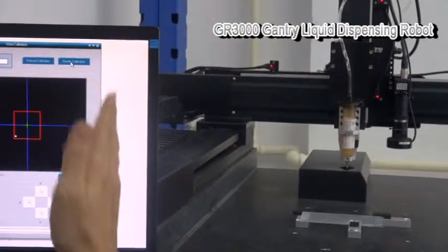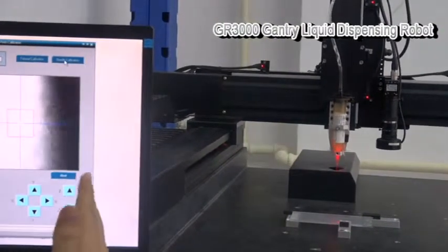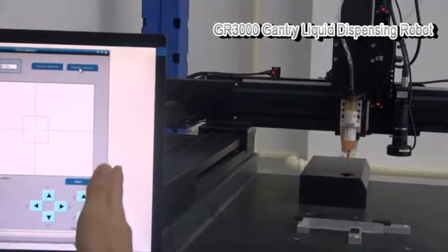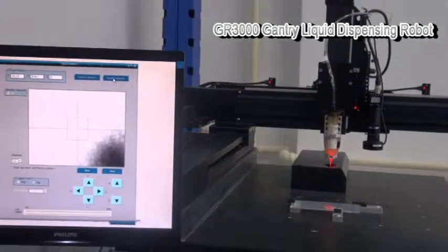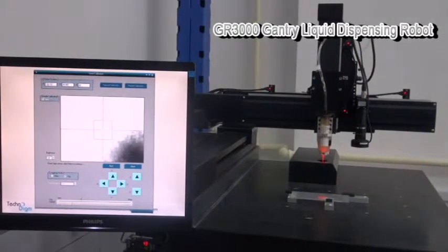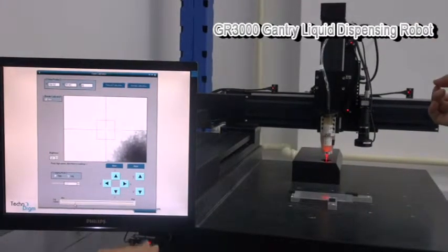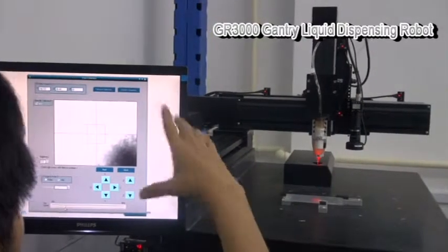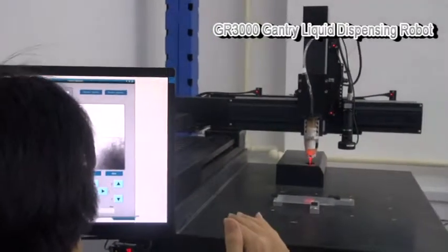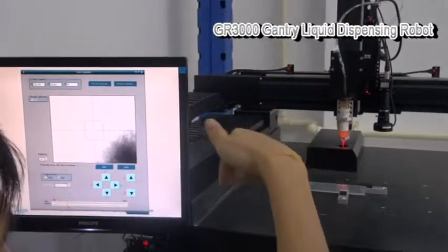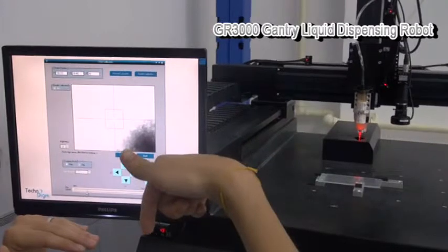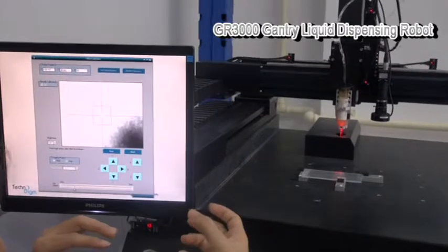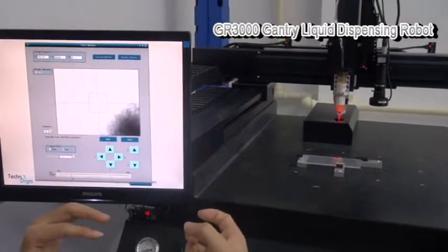Actually, the maintenance processes are mostly to teach the reference position. All this data will be used in the production and profile data. In our needle calibration process, the first thing, the machine will move down and let the laser detect the needle height, and then we use the camera to do the XY process.